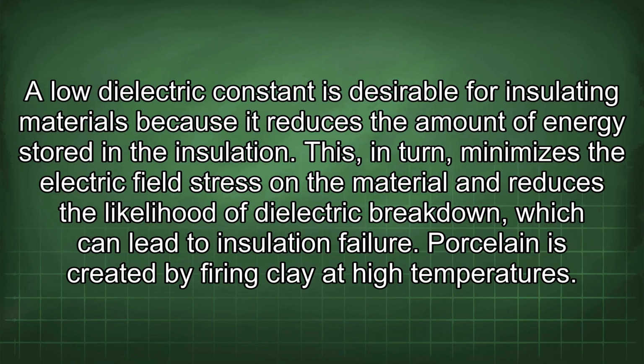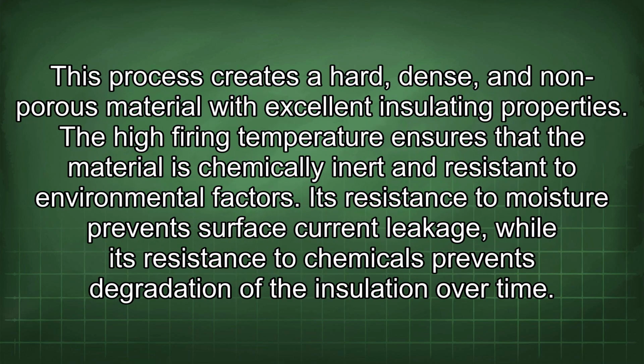Porcelain is created by firing clay at high temperatures. This process creates a hard, dense, and non-porous material with excellent insulating properties. The high firing temperature ensures that the material is chemically inert and resistant to environmental factors. Its resistance to moisture prevents surface current leakage, while its resistance to chemicals prevents degradation of the insulation over time.